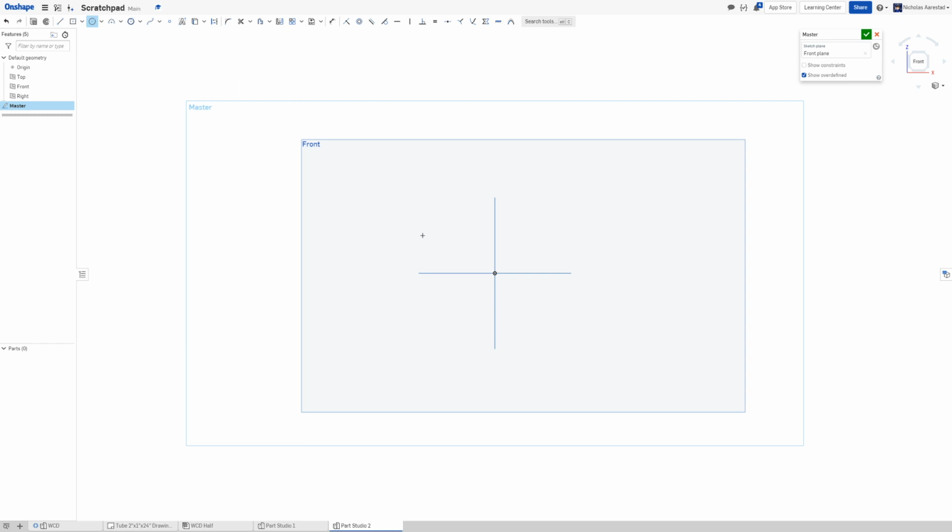In that case, instead of doing that, we can do something different, right? Which is constrain that on the origin. These planes are here to be useful to you. If you want something in the center, you want that center to be meaningful. So in this case, I'm going to make it that output shaft, because that's a meaningful thing to be in the center. And putting it in the center, on those things, will let me use these planes that you can see here to take advantage of symmetry in the design.